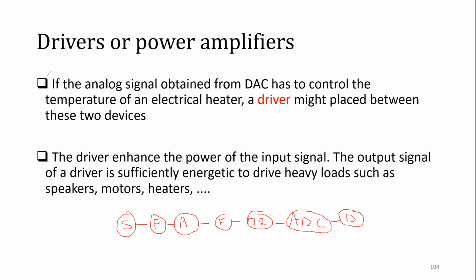For a control system, the system is a little different from what we saw last time. We have here maybe a microcontroller or something that processes the data, and then you have to control something, like in the case of a thermostat, you have to control the heater of the thermostat, right? So the thermostat is controlled by an electrical signal, which is analog. So we have to go back to the analog domain. So we need what is called a DAC, which is a digital to analog converter. And then we have what is called an actuator, which is the heater in the case of the thermostat, okay?